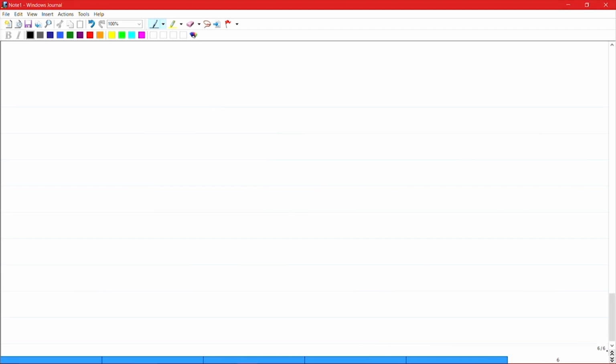Okay. Now, if you have an angle probe, then in that case these kind of cylindrical blocks cannot be used, because for an angle probe you need to calibrate the angle as well apart from the distances. Okay. So, when you have an angle probe, the block which is used is known as the IIW block, which stands for International Institute of Welding.